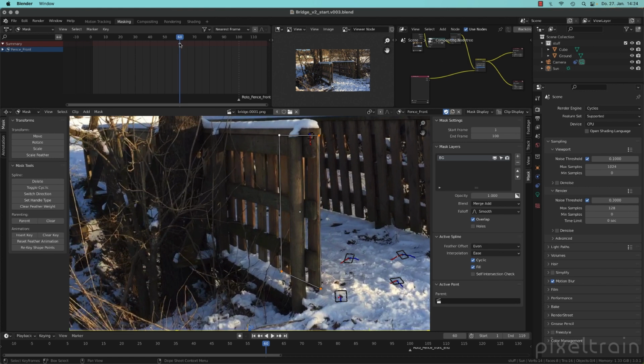What you also can do, and this is something I do now here, I activate the auto keyer, so every movement here is automatically keying. This helps me to not forget to press the I key, but I wanted to show you that you really can key also with the I key here. Now there are some really interesting things inside of Blender. I think maybe we can make a real compositor training later inside of Blender, so maybe that is the better place to do that, but only as a short notice.